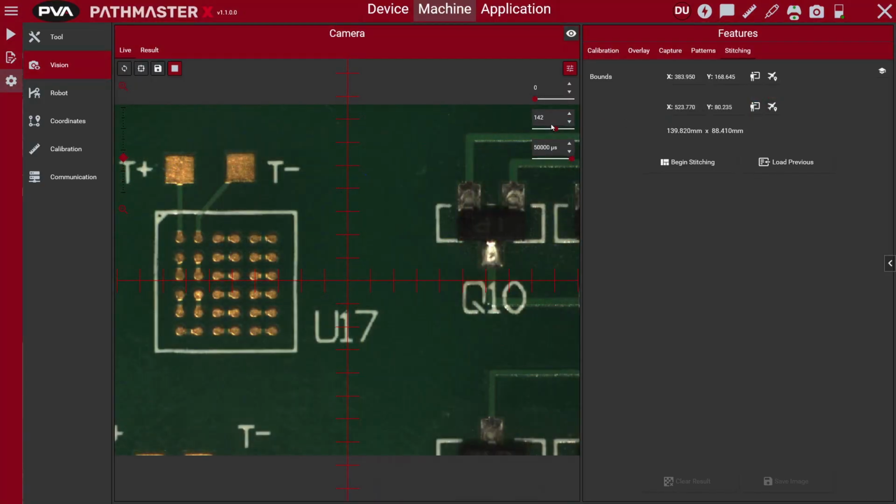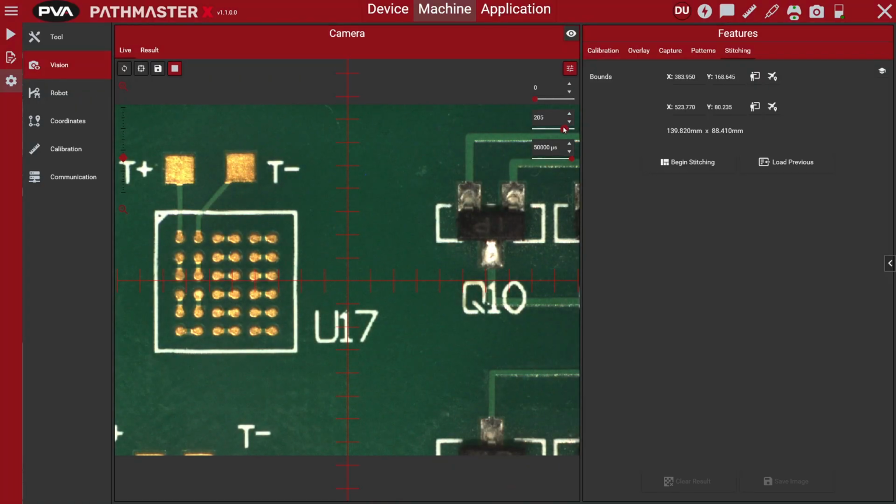Once the 2 points have been taught, adjust the image acquisition parameters using the camera interface and lighting options from the Quick Actions header menu until a clear image is attained. Using only the white light typically produces the best-looking stitched images. Before starting a stitch, be sure to stop grabbing live images as it slows the operation.